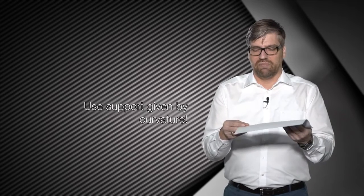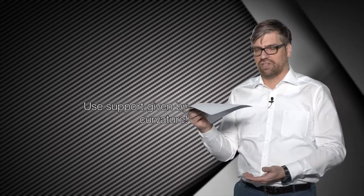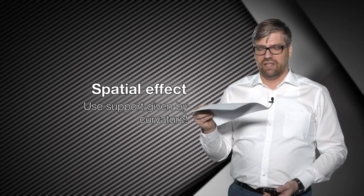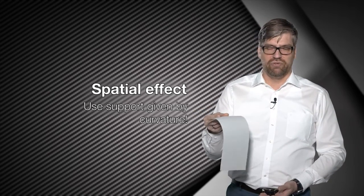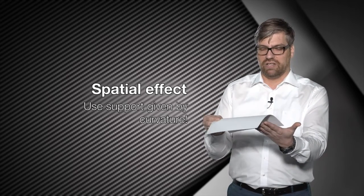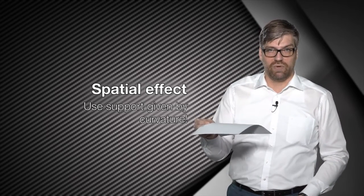And when you are in the situation that you have to use this plane and bad orientation of your structure, then please apply some curvature to your structure. Because when you apply some curvature to your structure, here you see, then you use the so-called spatial effect, and this increases the load carrying capacity of your structure significantly compared to pure plane structures. Just by applying a rather shallow curvature, I will see that the sheet of paper is able to carry its own weight.